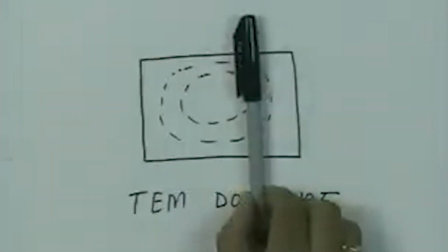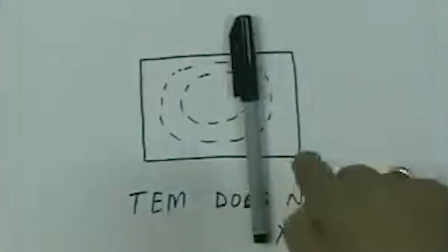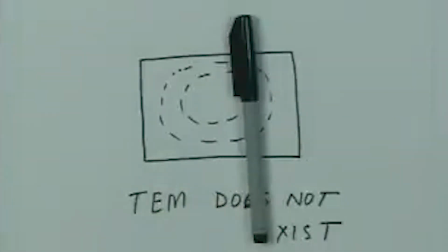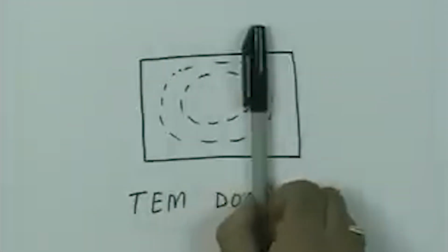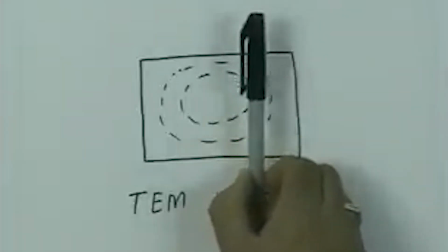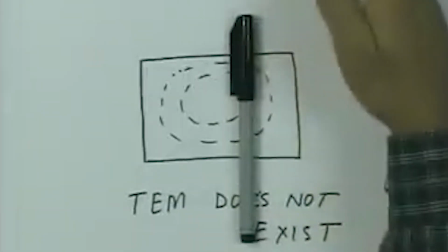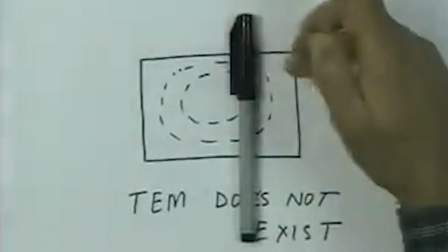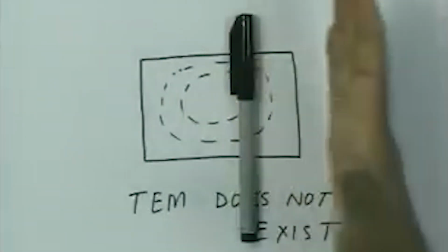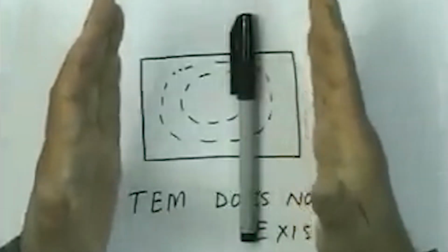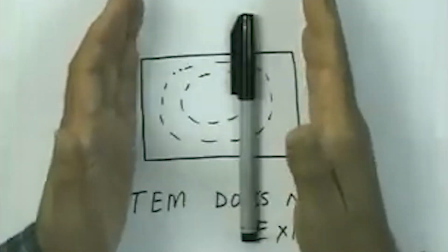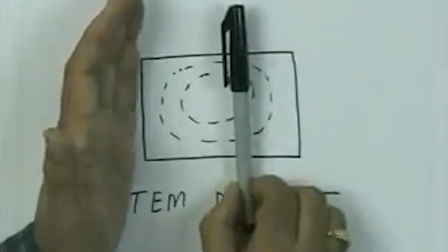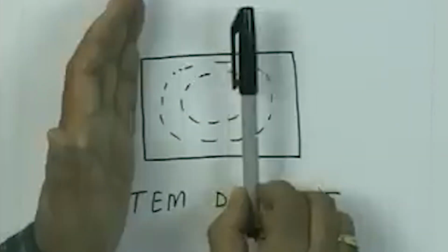And in this case, since the electric field is like this and the wave is going to propagate perpendicular to the plane of the paper, this mode essentially would correspond to the TE mode. So, by pushing the walls to infinity for the TE10 mode, I will get a geometry which will be the parallel plane geometry, and for this geometry the electric field is oriented like this. So, that will give me the transverse electric mode.